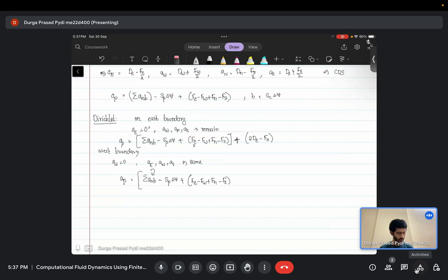And now because of your Dirichlet condition, you will have one additional term. It is on the west boundary, and because of Dirichlet you have 2 times dW, and then we also have the FW term that is getting subtracted here, which should not be there because of the Dirichlet condition, so you will have an additional FW here coming up.